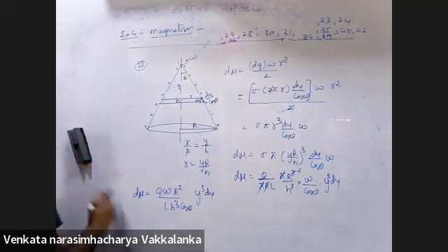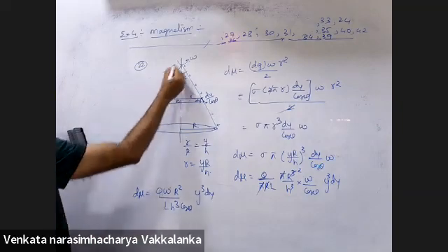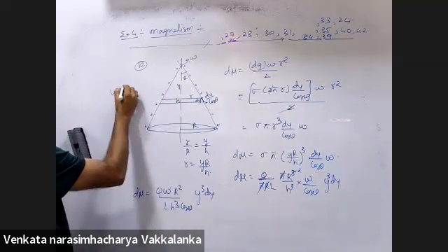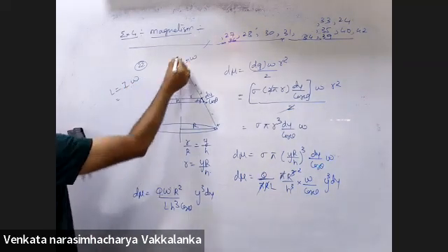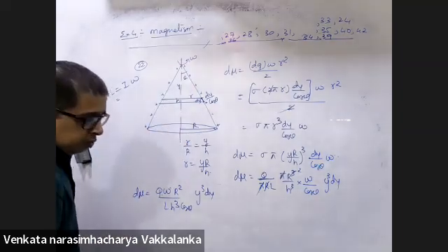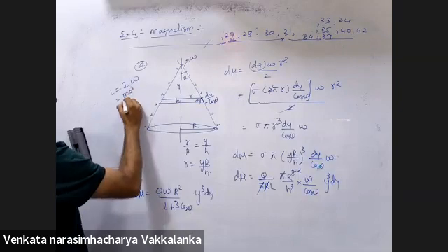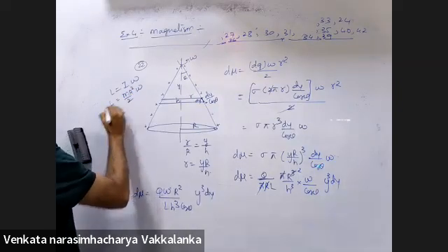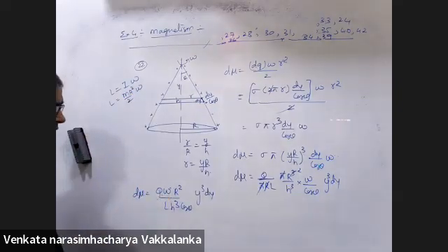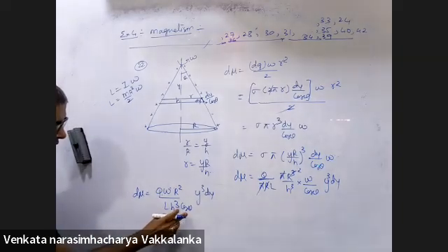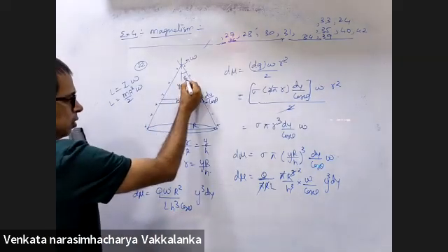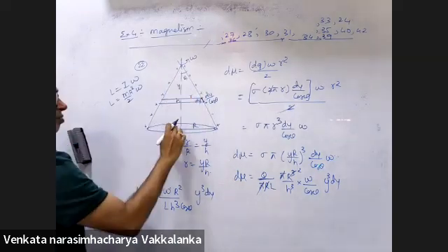But either way, what formula will you use for moment of inertia? L is equal to I omega. What is the I value for the cone? M R square by 2. So bring everything in terms of R. Cos theta, do you know the formula in terms of H?